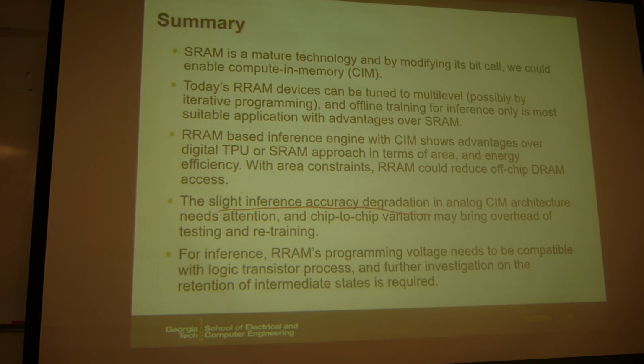So you need to fine-tune your neural network model to fit each chip, so you can recover the accuracy degradation for each chip. Of course, you need to spend more effort to fine-tune the model, and this is an additional cost for you, but it's possible. Of course, the ADC is also a challenge in this design, and we are still working on those problems in our group.